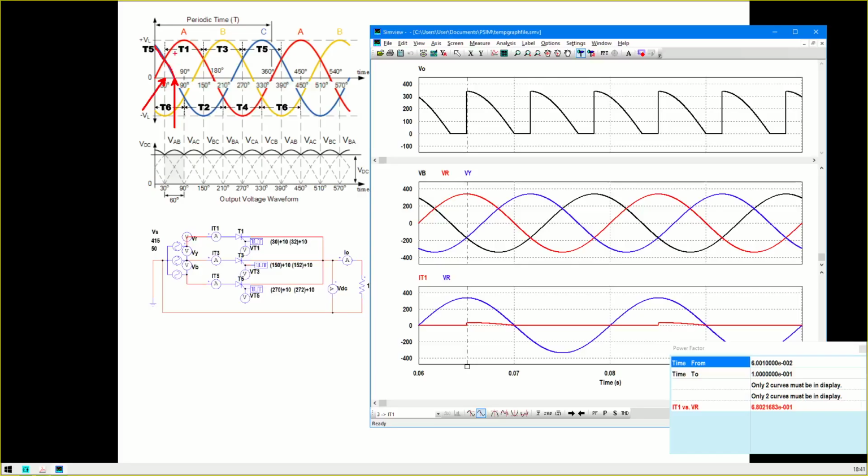Okay, for 30 degrees, and then when it goes beyond 30 degrees, since this is a purely resistive load, there is no current to force thyristor 5 to stay on, isn't it? So thyristor 5 will be turned off exactly after 30 degrees. And that's why you have this discontinuity up to 60°.